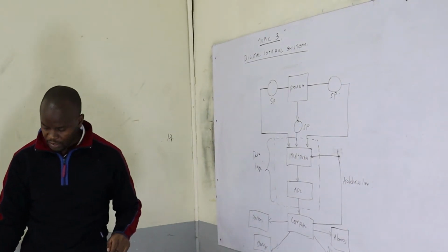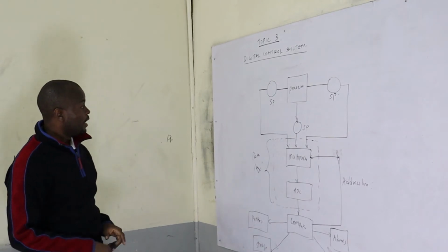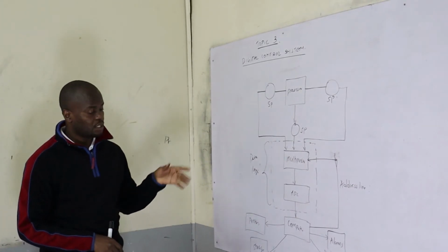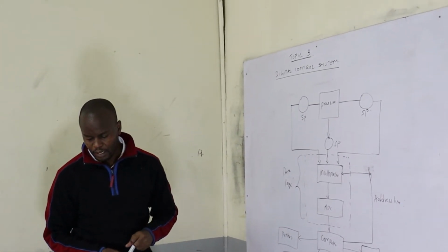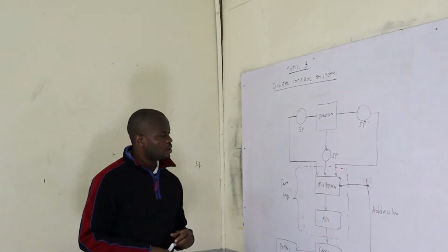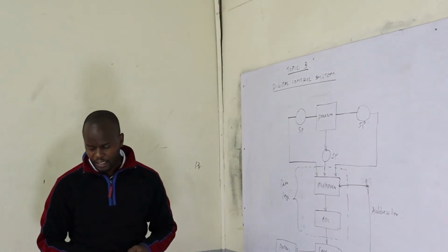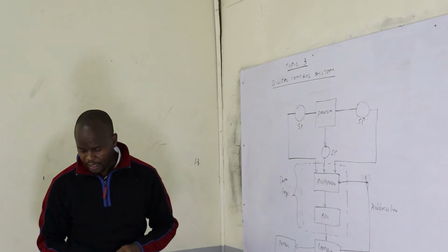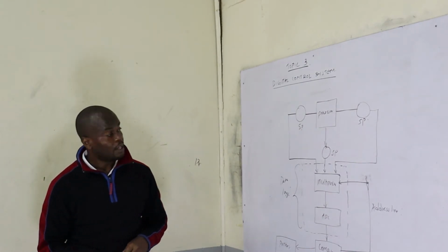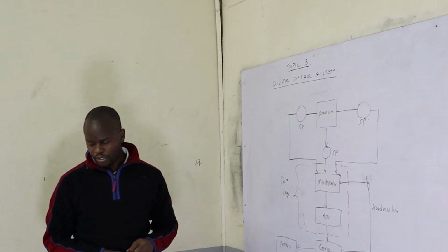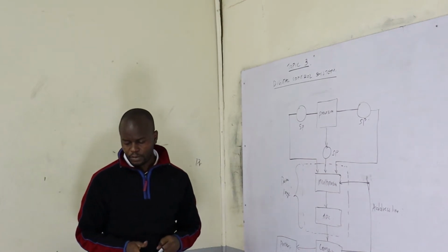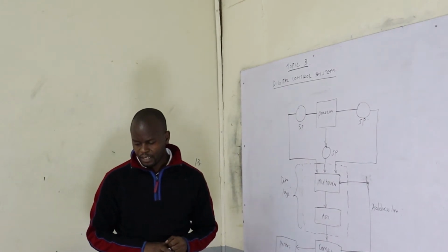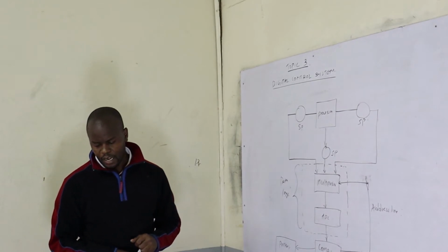It is acting as an interface between what is happening in the real world and what is happening in the digital computer. So in this case, if you talk about this process, it is always assumed that the process is under control of several loops, and there is always a provision for analog process variable measurements to be available. They are always available as scaled voltages, and therefore some signal conditioning converts all the measurements into a given specified voltage range as required by a data acquisition system.